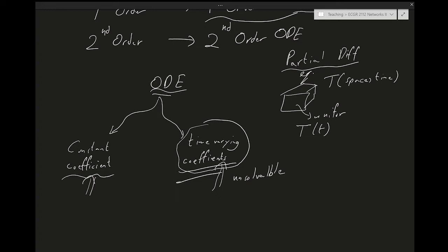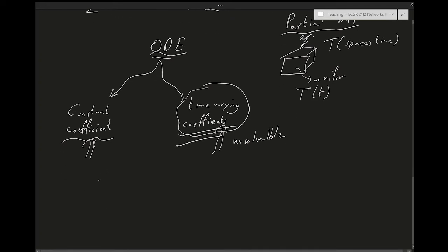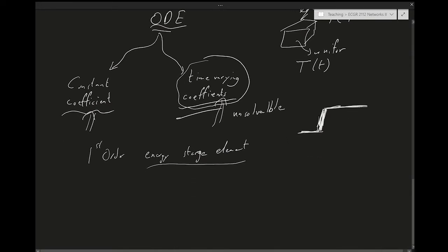And the dynamics of first order transients, so we're going to start with first order transients, are governed in your circuit. To have them at all, you need to have energy storage elements in your circuit. Or else, if you have a step change in the condition of your circuit, either the network or the voltage, and you don't have any of those energy storage elements, nothing will happen. You'll just have a step in your solution. Only if you have the energy storage element will you have this transient behavior that you need to study.